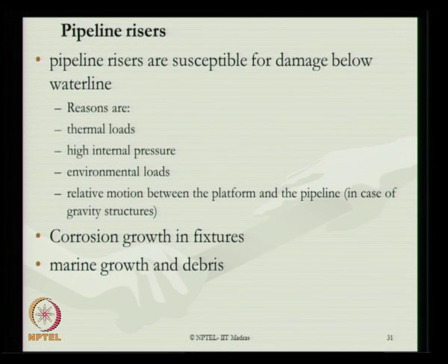Now, NDT as applied to pipeline risers also plays a very interesting area of domain of research. Pipeline risers are generally susceptible to damage below the waterline. The reasons are thermal loads, high internal pressure, environmental loads and relative motion between the platform and the pipeline in case of gravity structures.